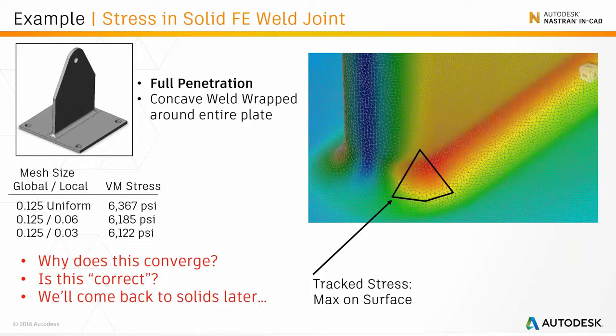What happens if we assume that everything is bonded and we have a nice smooth weld around the side that maps to a post-welding grinding operation? Sure, it will converge, but does this match reality? In most cases, people are trying to make their finite element model give them answers that don't match anything that's happening in reality.